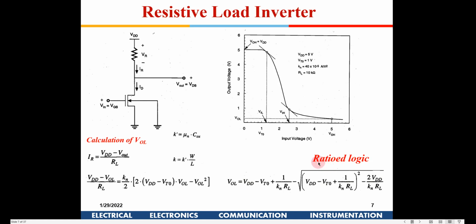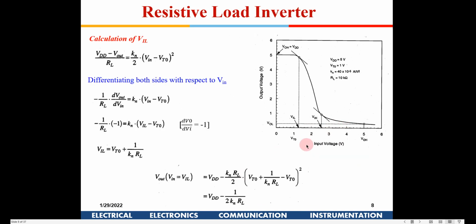So why don't we use the small VDS equation here? We are not assuming it to be too small, so it is in a linear region. The small VDS equation is generally used for deep triode. What is also important: the initial short circuit current is less when the gate voltage is rising. We are not discussing anything about the transient as of now.